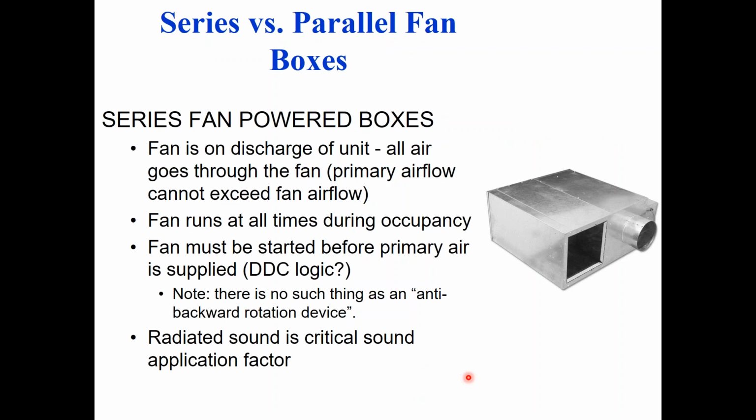However, I did not mention and should have, if that particular zone needs heat in the middle of the night, instead of turning an air handler on to bring heat, he will just turn this fan on and then he will turn on this guy's electric heat or hot water coil and just heat this one zone. And then when the heating call is over at nighttime for that zone, he'll just shut it back off.